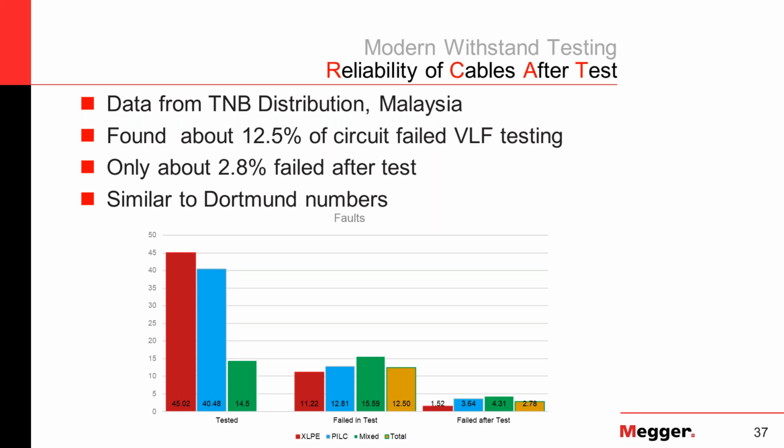You need to do it at 0.1 hertz, and if you cannot do it, you need a better test set. That's pretty much what IEC is saying. They take a technical and scientific stand, saying, well, you need to bring a proper test set so you don't deviate from 0.1 hertz. And pretty much this study in Malaysia is the statistical proof that the failure rate is higher.